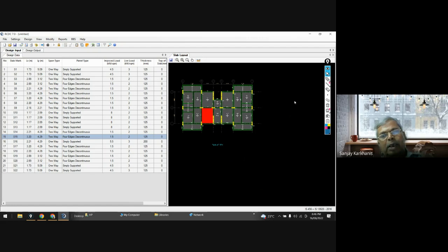See, many times I ask people why we are finding bending moment. Just we don't have any work to do. Why we are interested in finding shear force? Why we are interested in finding bending moment? Because they provide us some information where we should provide a reinforcement, how we should provide a reinforcement, and what amount of reinforcement is required so that that portion will not get cracked.